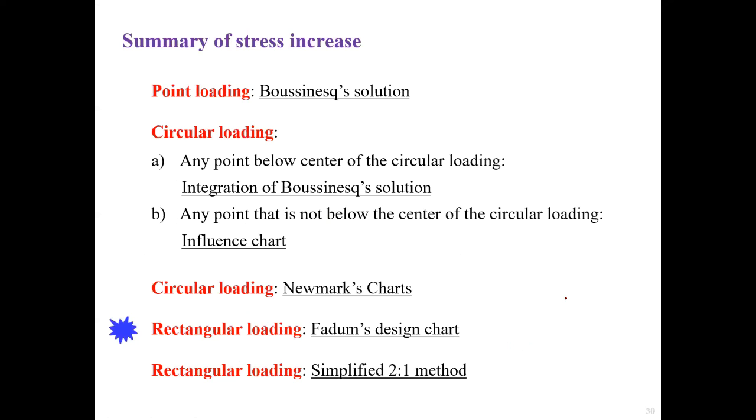And finally, I'd like to provide a summary of the stress increase, what we have learned from this lecture. For point load, we use the Boussinesq solution. If you have any point on the ground, we have a Boussinesq analytical solution to calculate the stress increase. So for any point below the ground at point A, we are able to refer to that formula to do the calculation. And then for the circular loading, any point below the center of the circular loading.